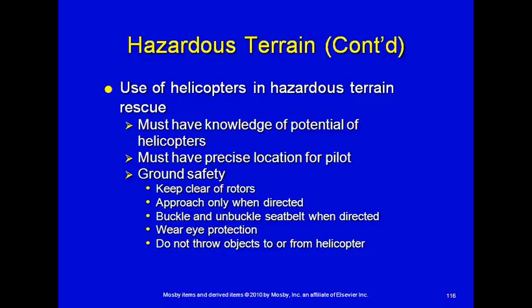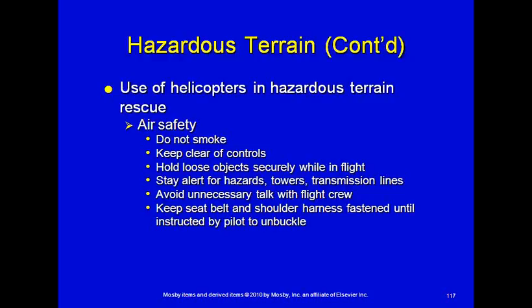All the ground safety needs to occur as well, as far as keeping clear of the rear rotors. Approach the helicopter only when directed by the pilot. Buckle and unbuckle your seatbelt when directed. Wear eye protection. Don't throw objects to or from the helicopter. Don't smoke. Keep clear of controls. Hold loose objects securely. Stay alert for hazards, towers, lines, trees. Avoid unnecessary talk with the flight crew. Keep the seatbelt and shoulder harness fastened until you're instructed by the pilot to unbuckle.